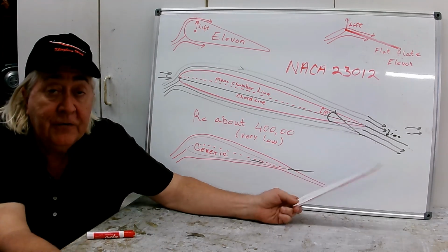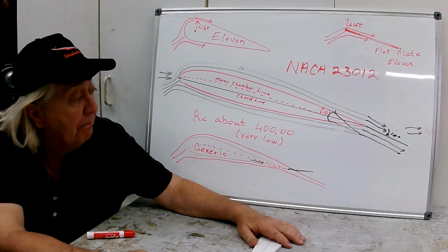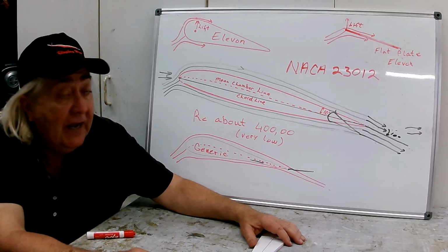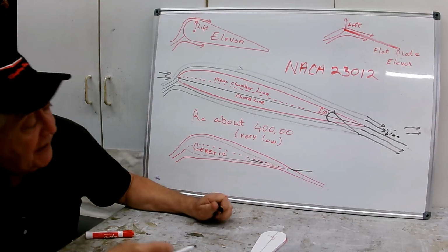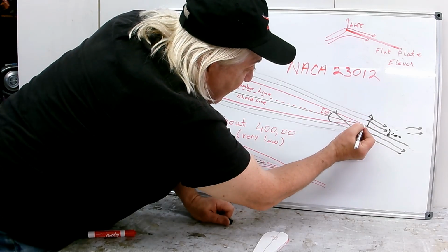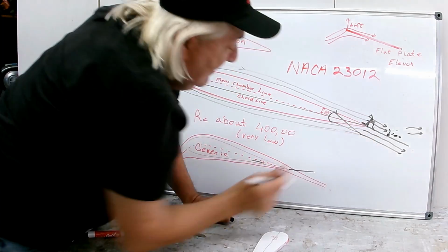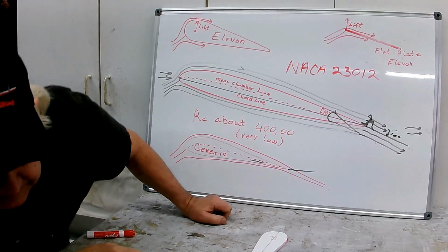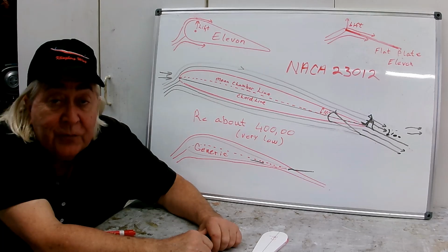So the first 10 degrees, in my mind, you get free. You're not mucking up the flow for the first 10 degrees, and then I get about another 12 before the standard separation kicks in, because as you go past the 10 degrees, you start generating some lift here, you cause that little spike in the pressure, and once again, once I start causing that discontinuity, I'm only good for about another 12 degrees.